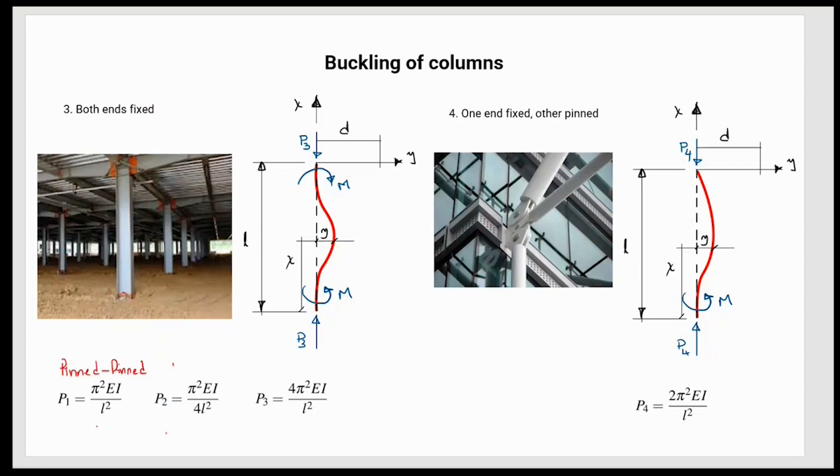If we consider the fixed-free, what I said was that it requires less load to produce buckling in the column. Now, if I come to this case here, what this says is that it requires more load to produce buckling in the column with respect to the reference case.